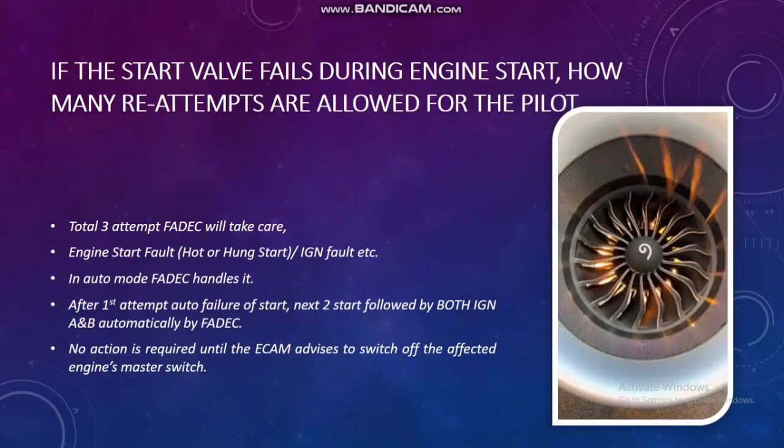Now another question is: if the starter valve failed during the engine start, how many re-attempts are allowed for the pilot? So this is a scenario. Total 3 attempts, FADEC will take care. Engine start fault, hot or hung for any reason, or ignition fault. In auto mode, FADEC will handle everything.